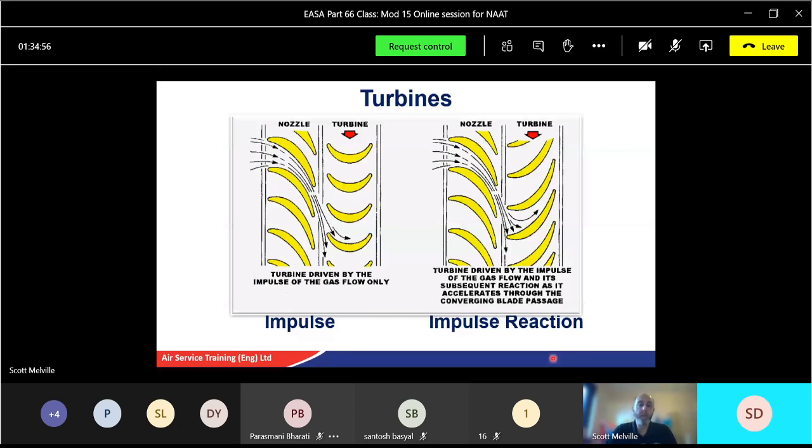And again, depending on how many stages, if it's a 2-stage turbine, a 3-stage turbine, or even a 4-stage turbine, we need to extract as much energy from the gas as possible. And remember, yesterday we also spoke about how usually a turboprop engine will tend to have more turbine stages than a general gas turbine engine. Okay, a good one to remember there. The reason being, we want to extract more energy to help propel that propeller that's attached to the end of the shaft.